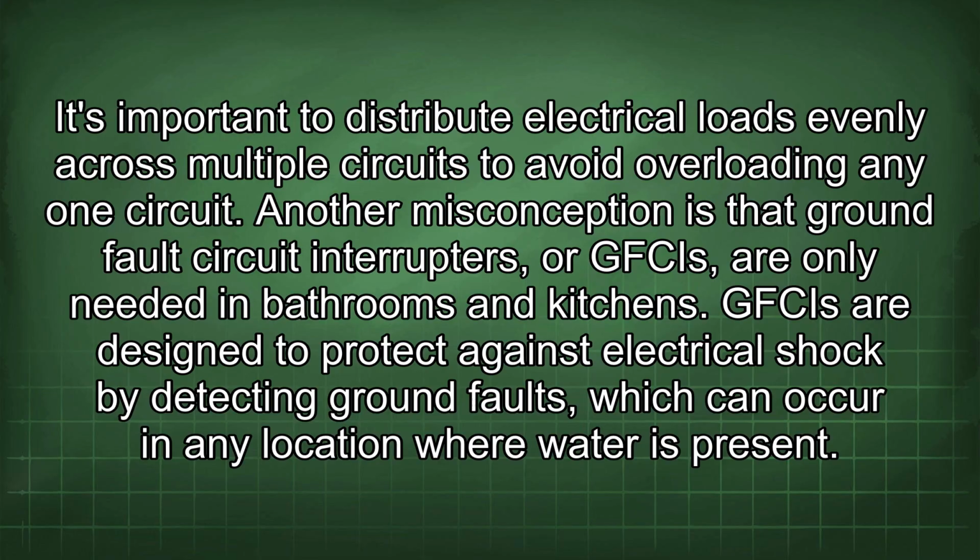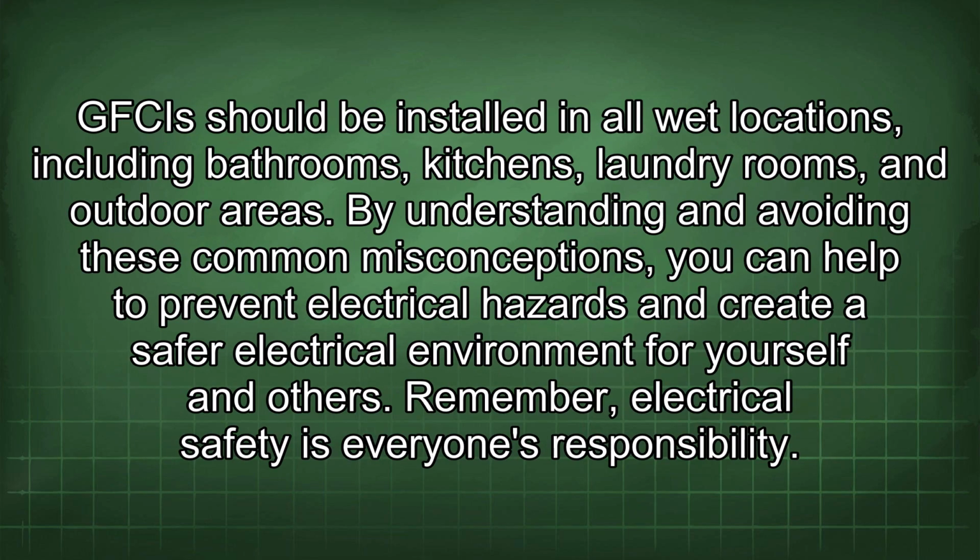Another misconception is that ground fault circuit interrupters, or GFCIs, are only needed in bathrooms and kitchens. GFCIs are designed to protect against electrical shock by detecting ground faults, which can occur in any location where water is present. GFCIs should be installed in all wet locations, including bathrooms, kitchens, laundry rooms, and outdoor areas.